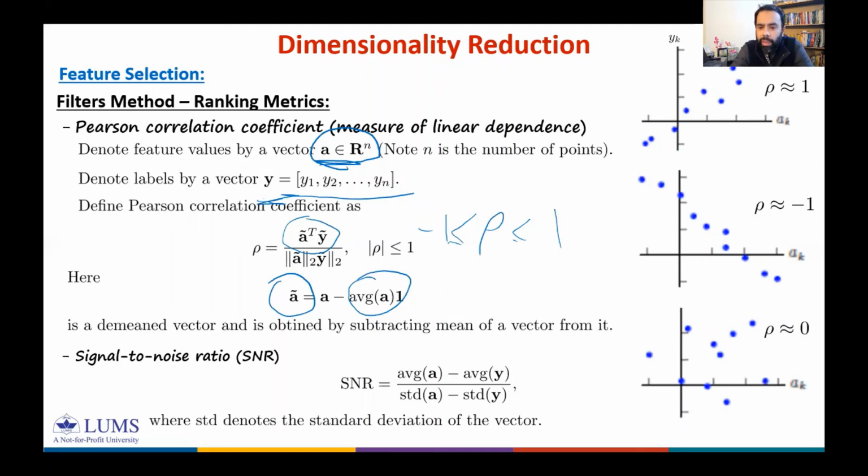So this alternative definition is used for variables that are always non-negative. For example, we have some counting, because counts are always greater than or equal to 0. Images, pixel values, are always greater than or equal to 0. So in image processing, the SNR of an image is usually calculated as the ratio of the mean pixel value to the standard deviation of the pixel value over a given neighborhood. And in that scenario, in image processing, we use this definition of signal to noise ratio.